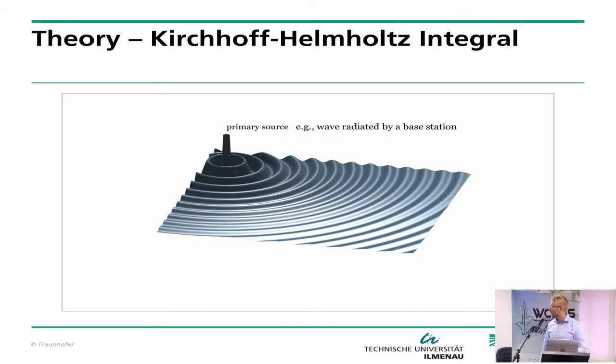So this is nice, but to realize monopole and dipole sources at the same position is hard. We would need different kinds of antennas at the same position. That's not easy. So we just remove one part and stick to monopoles or to dipoles, and then we have the same field inside again, but outside some mirror effect. But it's not a problem, because if we have a chamber with absorbers, we can absorb the field that goes to the back, and we have proper field conditions inside.